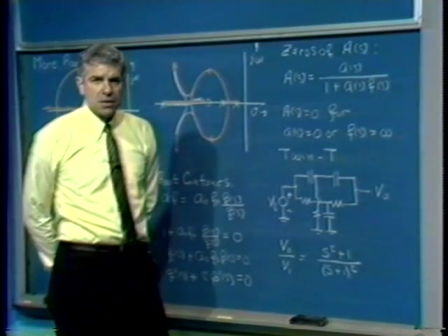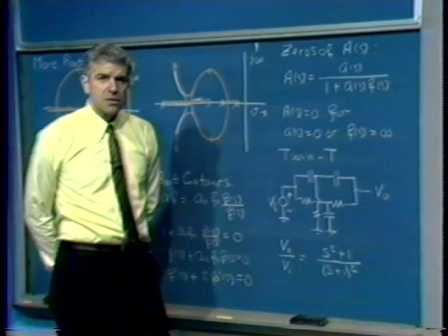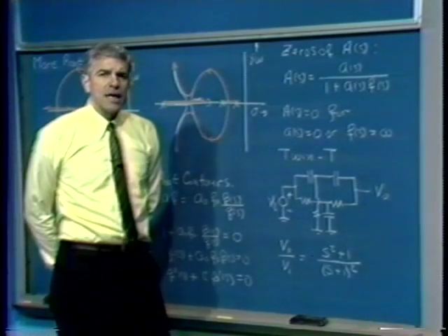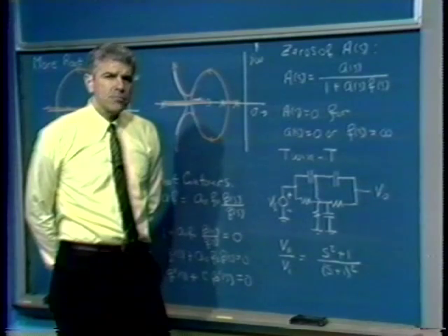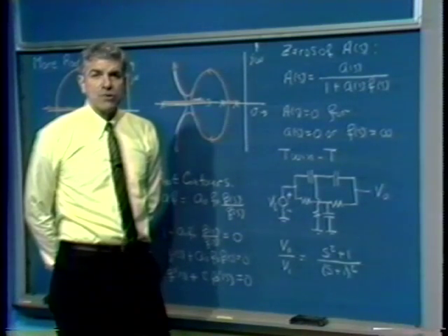Again, by the argument that I earlier used, that the number of poles and zeros has to be the same so that the high frequency gain is a constant with increasing frequency, we'd have to have 3 zeros. If, once again, we select component values correctly, the third pole and the third zero can be made to cancel. In that case, we get a transfer function which includes 2 zeros divided by 2 poles.